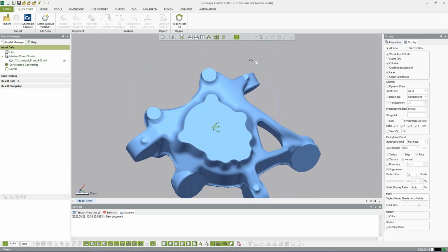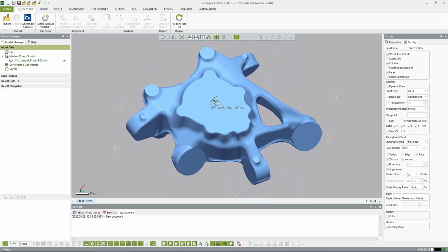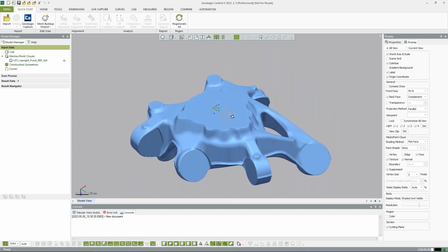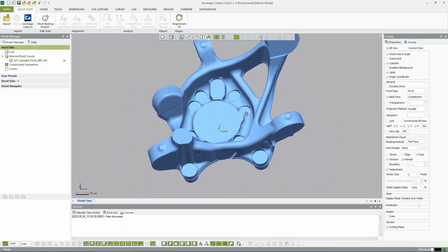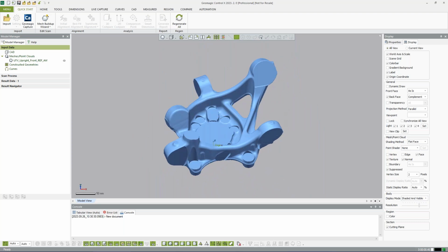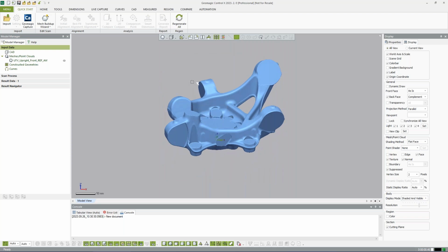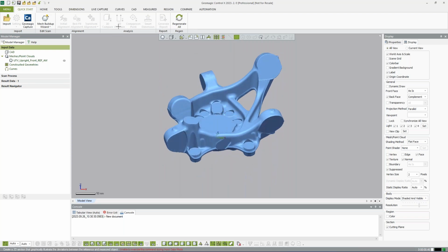Often, even with normal CAD workflows, the CAD origin, where it's drawn, may not be what's on your print. So a lot of times if we want to do ordinate dimensions on prints coming from the left hand of a part, that we want to check and send back to machining, the input data is where you're going to do all of that translation of CAD objects, if you want to move stuff and have it just set and change things on the CAD bodies.